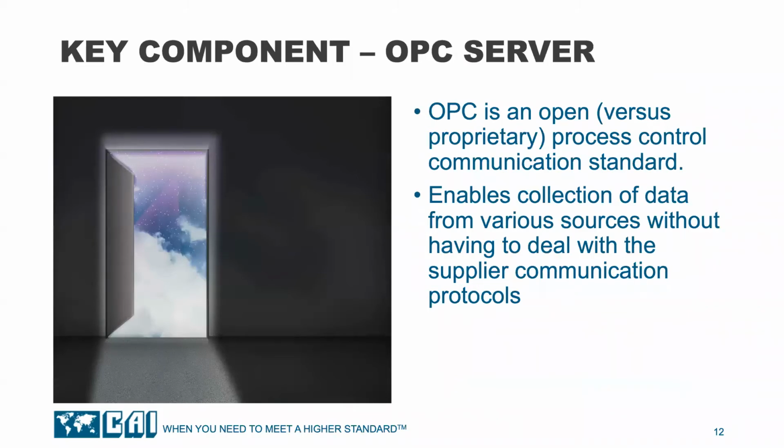OPC is an open process communication standard. Before OPC, if you were developing a data historian or other system to interface with a vendor's control system, you would have to pay the vendor for the details of their communications protocol in order to interface with it.